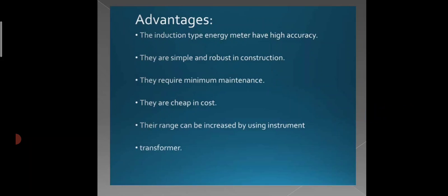These are the advantages of the induction type energy meter. They have high accuracy, and they are simple and robust in construction. They require minimum maintenance. They are cheap in cost. Their range can be increased by using instrument transformers.